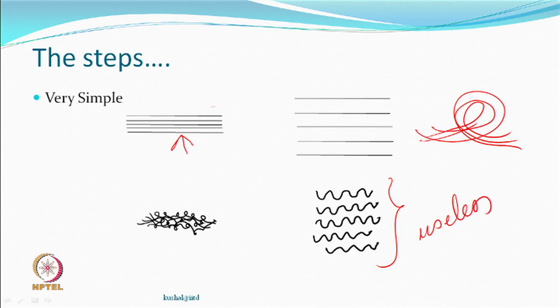This, if it does not happen and bends like this, is bad. And so, you would require some amount of entanglement where the loops are projecting out and there is some area within the yarn which obviously is not protruding out, but it is still hopefully holding the different filaments at positions which are a little more separate than otherwise they would have been. So, you increase the bulk, right.